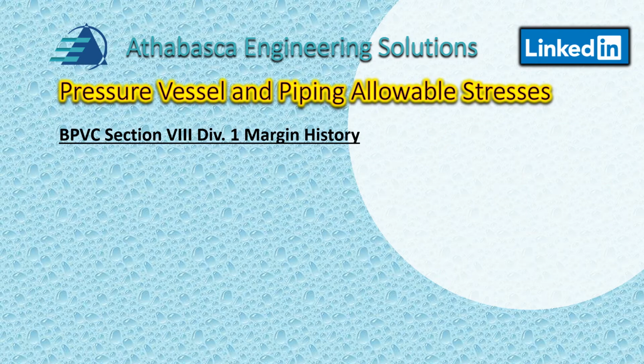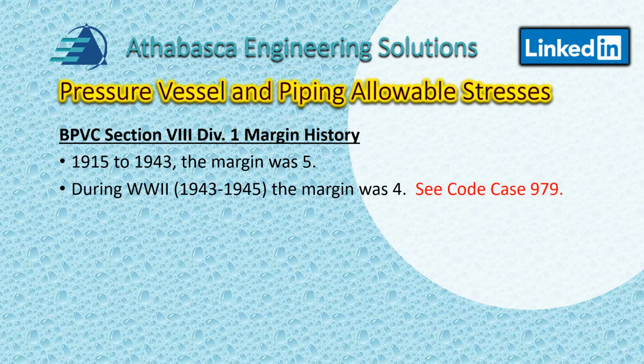Okay, let's look at the history of Section 8 Division 1. From 1915 to 1943, the margin was actually very conservative. It was 5. During World War II, between 1943 and 1945, the margin was 4. And the details can be found in Code Case 979.